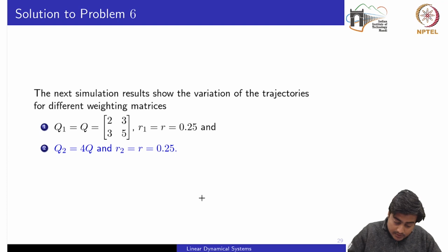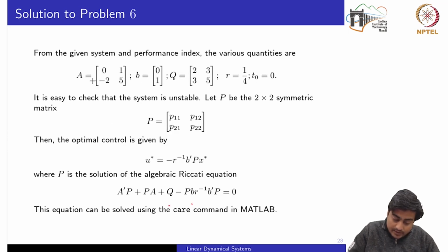Right, so now we would go directly onto the simulations, because this information is already given to us, A, B, Q, R. Now using this information, by using the derivations we had seen in the lecture slides, you can compute directly this control law, where P you can compute by this one. So A and B are fixed because of the system dynamics.